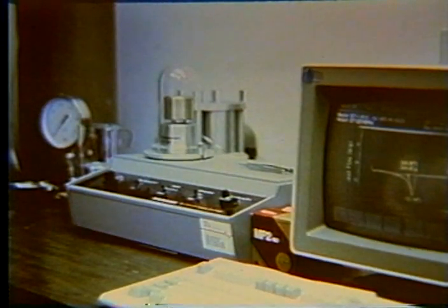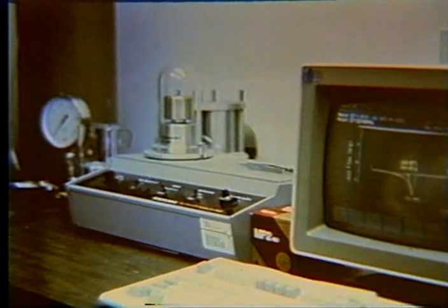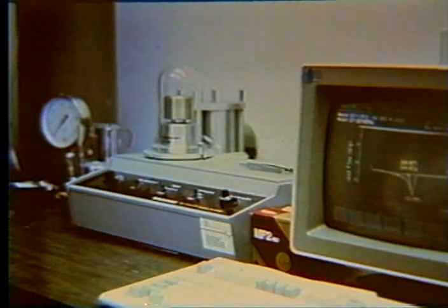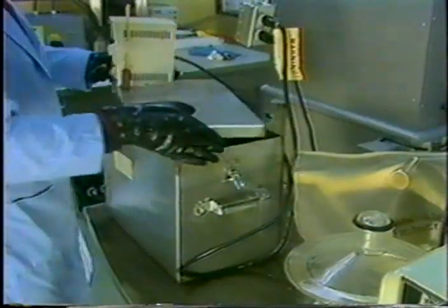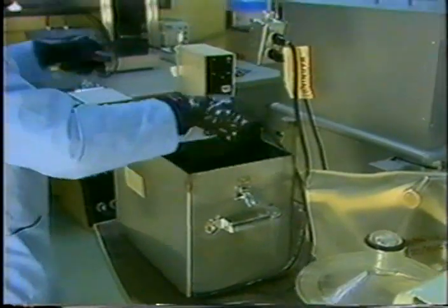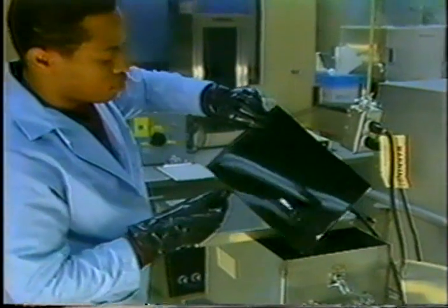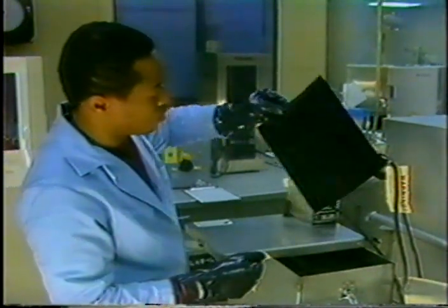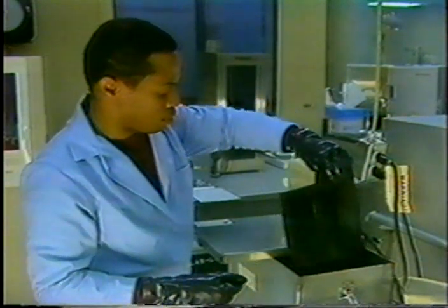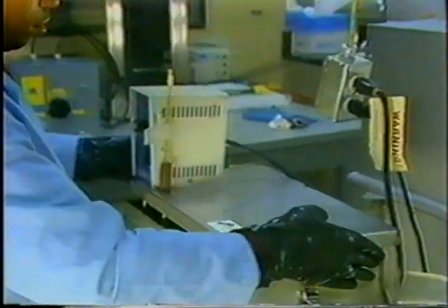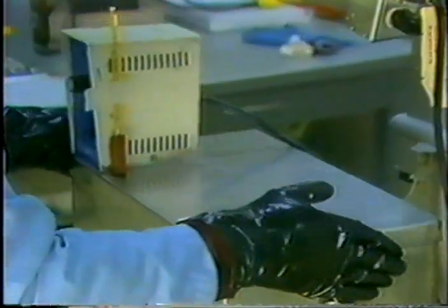Tests like differential scanning calorimetry, or DSC, indicate a material's response to heat, which demonstrates some of the properties of its polymer structure. To test chemical compatibility, samples of the candidate geomembrane are immersed in the site leachate at given temperatures. At intervals of a fixed number of days, the samples are taken out and tested for a range of characteristics such as changes in dimension, mass, and strength.